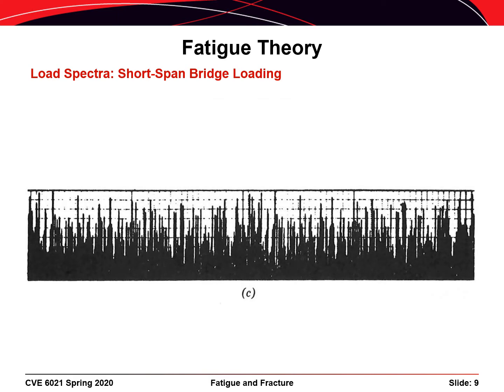This slide shows a load spectrum for a short span bridge over some period of time, maybe over the length of one day. Note that this is relatively variable in terms of the peak loads that are observed. That is one of the challenges of fatigue theory with respect to bridges. That is the high variability in loads that pass over the bridge on a day-to-day basis.